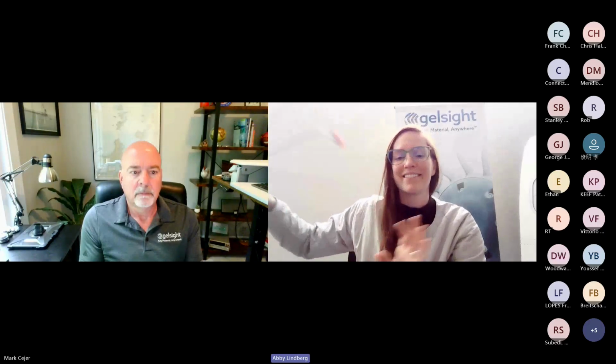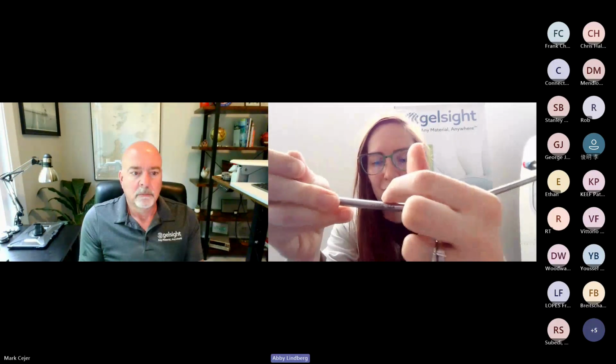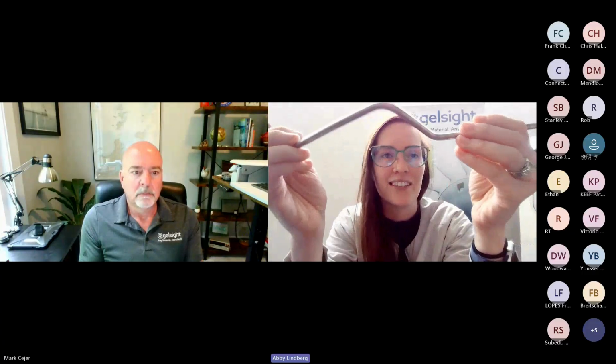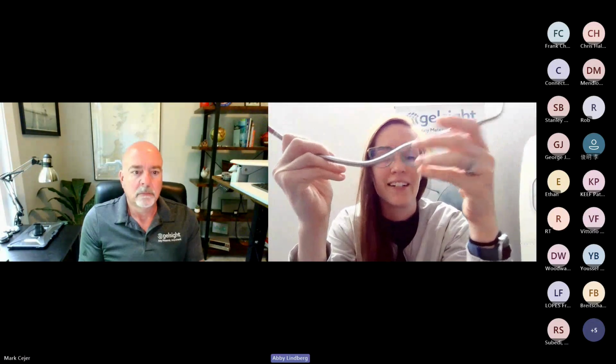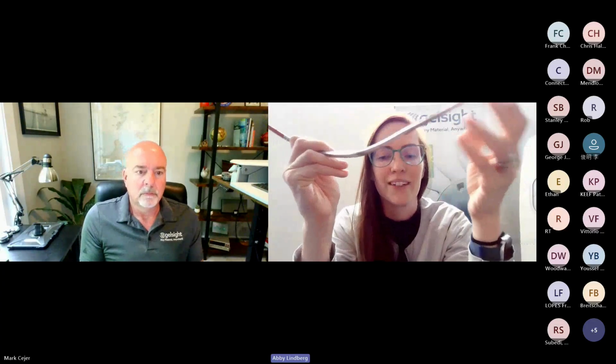All right, factoring in the radius of small diameter tubing, how do you measure a gouge from what was the peak of the tube? Okay, I'm assuming, and I could be wrong, that we're talking about a gouge on this edge here. I did use our defect detection function, and that automatically fits a second order form to it, so we can handle curved surfaces or flat surfaces.